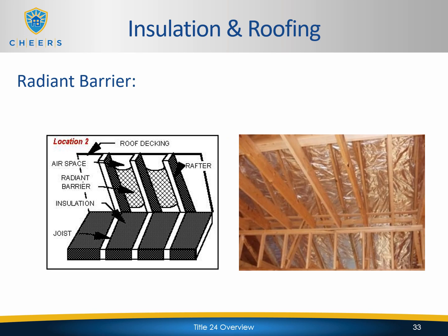Now in this particular installation type, it's a two-step approach. So they basically roll the radiant barrier over the trusses and then they put the roof sheathing over it.